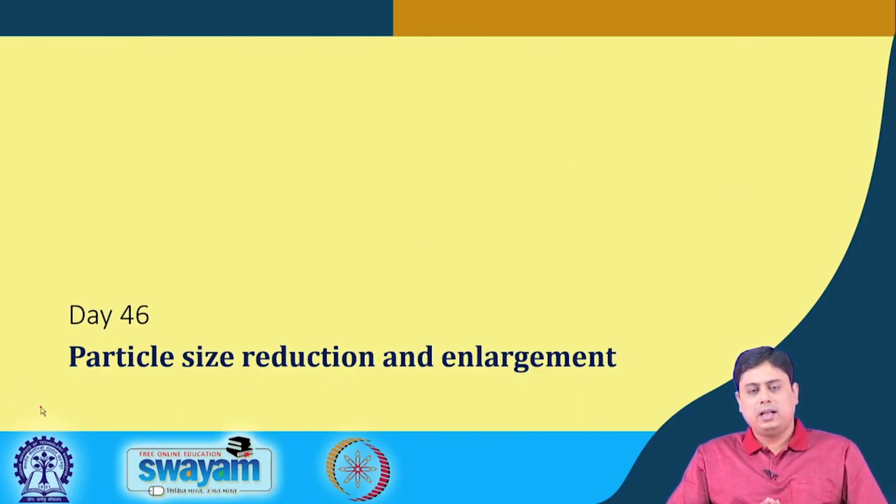During this particle breakage or particle size reduction, we have seen the amount of energy it consumes, in three different laws in chronological order, starting from Rittinger's law, Kick's law and Bond's law. With a couple of examples, we have seen the utility of these laws, how they help in estimating a primary guess value of the energy requirement.